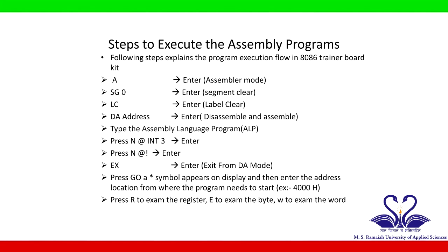Deassemble and assemble. Type the assembly language program ALP. Type N at int3. Enter. Type N at exclamatory. Enter. Type EX. Enter. Exit from DA mode.